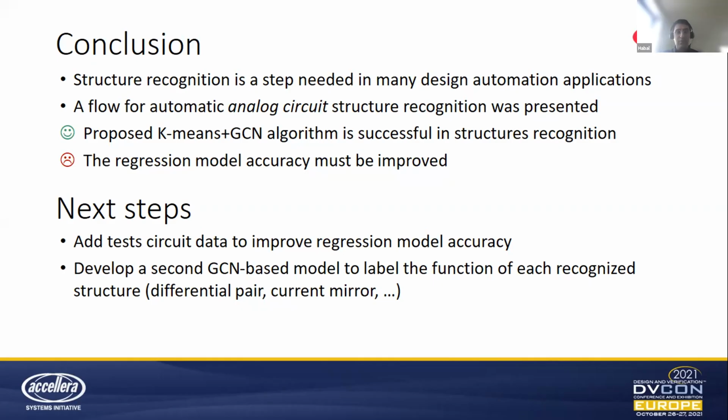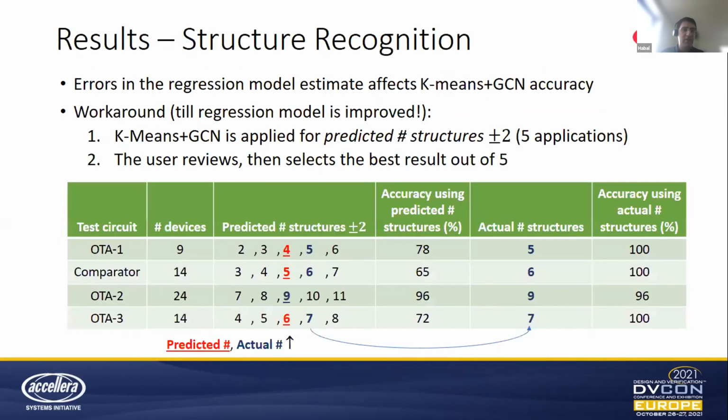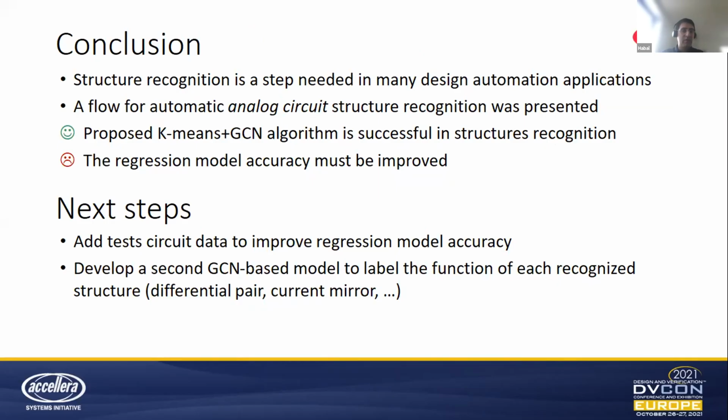So one tool that we use is Cadence Virtuoso. It's a commercial tool. And this tool has a built-in constraints manager. You can define in this manually, usually, constraints over a bunch of transistors. And these constraints are then read when you do placement and routing. So when you place the devices in the layout view, it can then be done in a certain way. So it can then put the devices with dummies around them, right, to avoid mismatch. So this is one application.